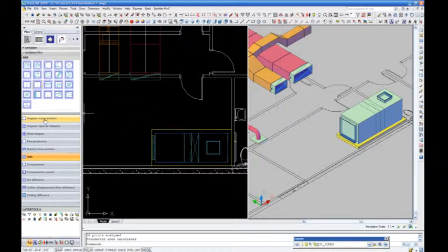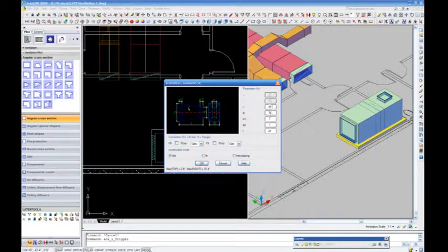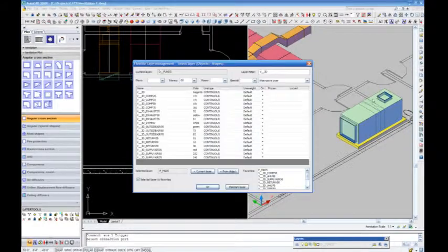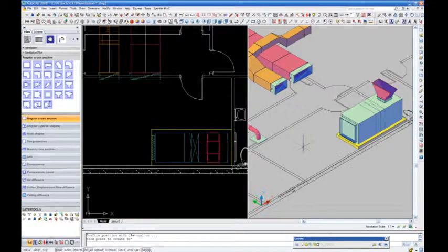The pad is placed. We will begin our design of the ductwork connections from the unit connections to the fire dampers. Here you will view the means of connection that are unique to the CATS software product. We will begin by placing a transition on the supply air duct flexible connection. By selecting the flex connector, the flexible layer management appears, prompting us to select another layer for supply air duct within the mechanical room.